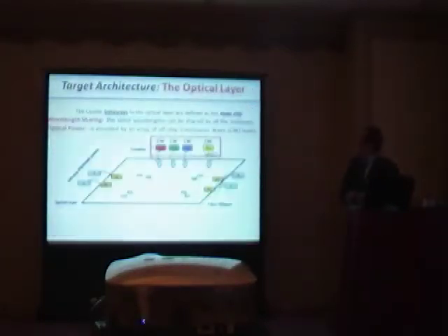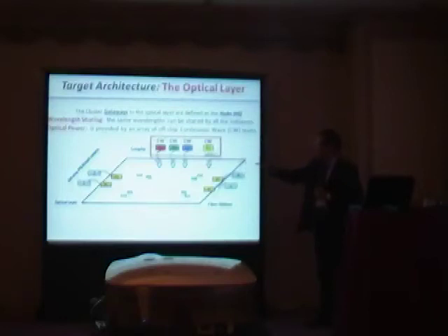The optical layer instead consists of 4 gateways, which here are named hubs, H1, H2, H3 and H4. It also equips 4 memory controllers, M1, M2, M3 and M4, which are connected by using fiber ribbon with chip DRAM DIMMs. As I said before, we use an array of continuous wave lasers, where each of them is tuned on a precise wavelength, like lambda 1, 2, and 3, and so on. Notice that the same wavelengths can be shared by all initiators, and then hubs and memory controllers too.